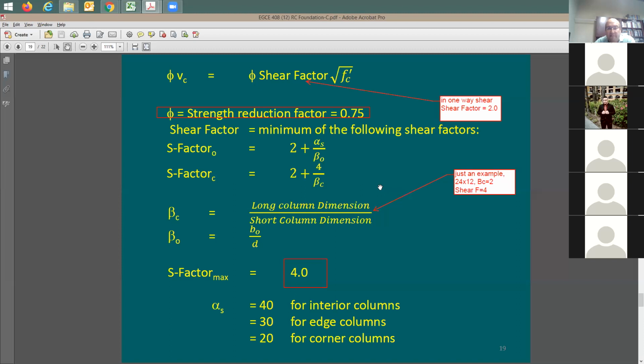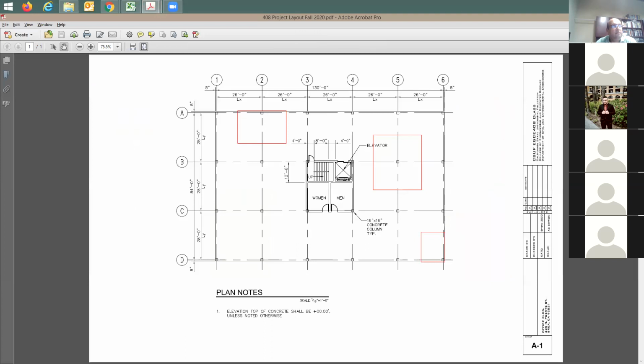Just for clarification, how does it work? I know the beam load goes through the tributary length of the beam to the column. For example, if we have only one kind of beam in that tributary area, with a length of 20 feet in total, then only that 20 feet contributes in that section.